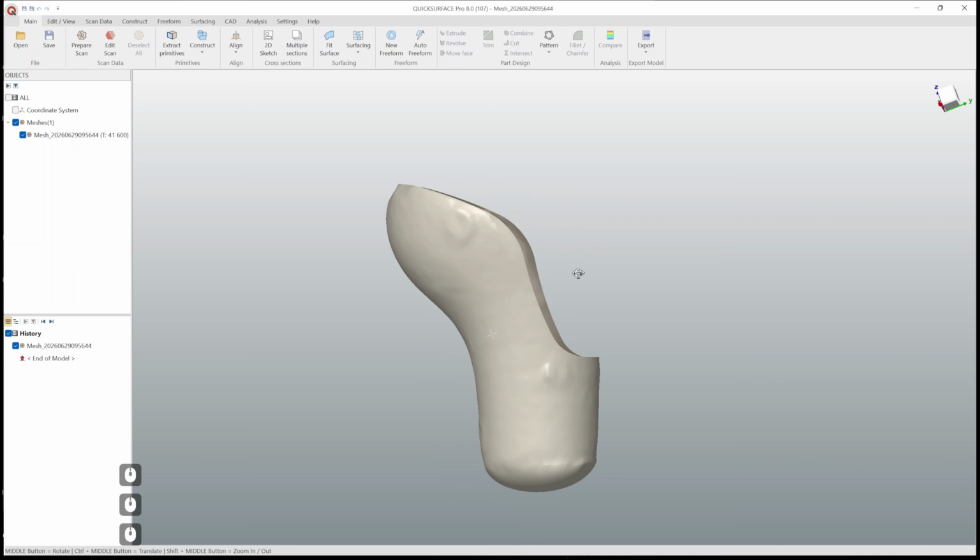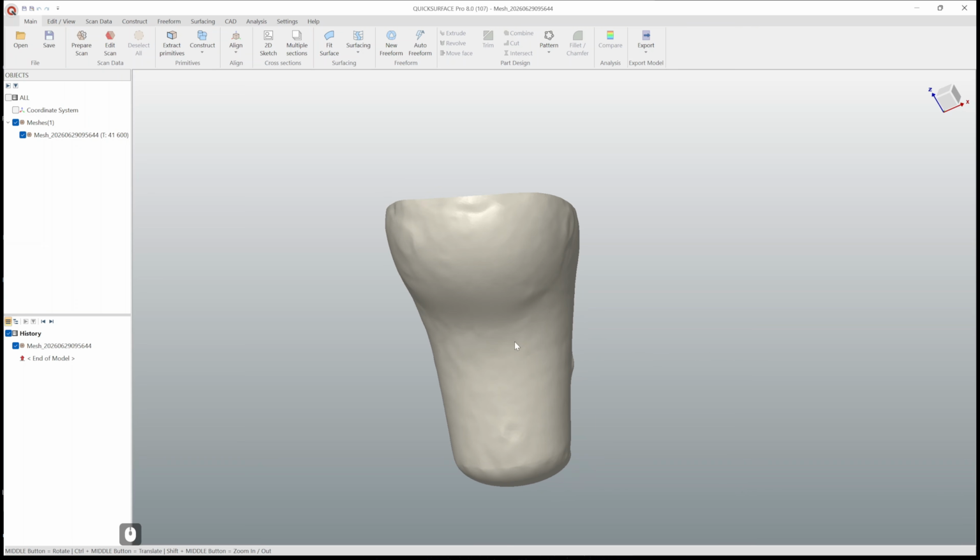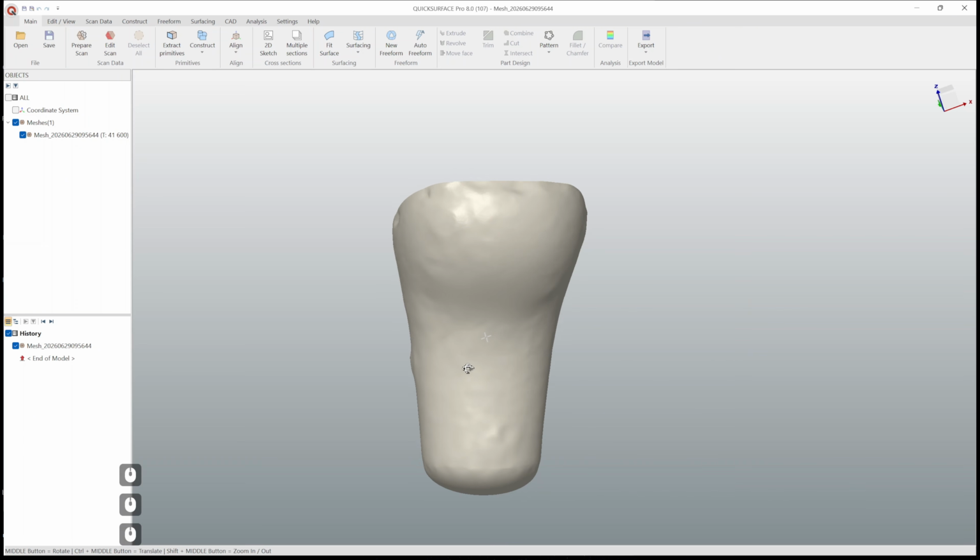Right now I'm looking at this part and I can see several approaches. So first we can try to fit some primitives, then loft all that together. Probably this might work, but there is never a guarantee that it will work. Same, we can try to create a 3D curves network and then create a fill surface based on that.